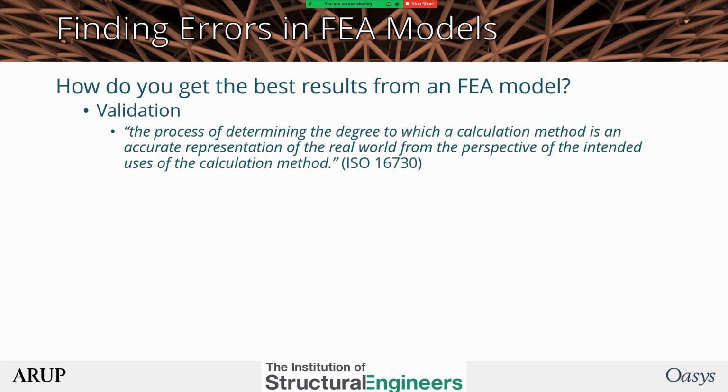The CTV building analysis model was also invalid because they did check for seismic, but they only got center point story drift output. The building had an asymmetric stability system, so torsional drift was significant, and that's what led to collapse.